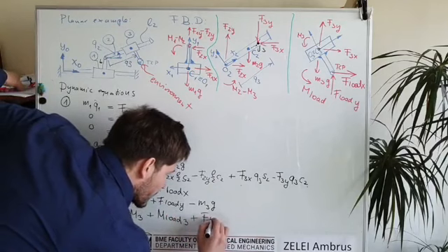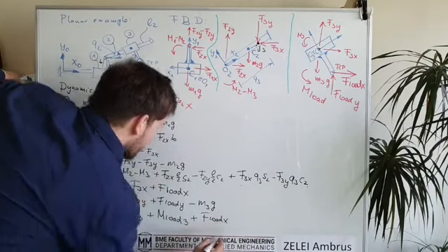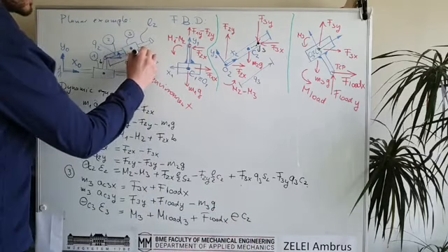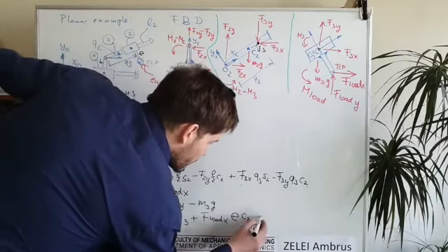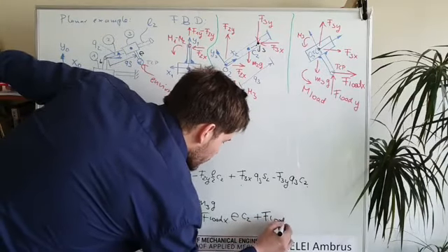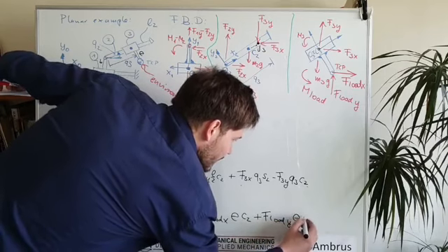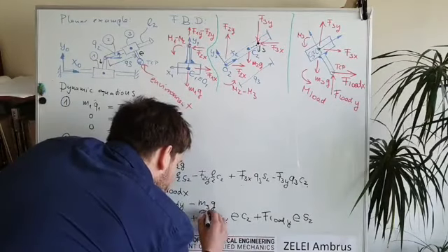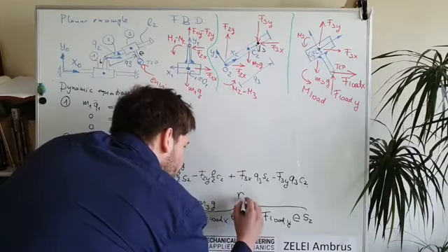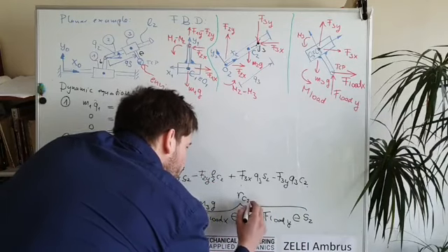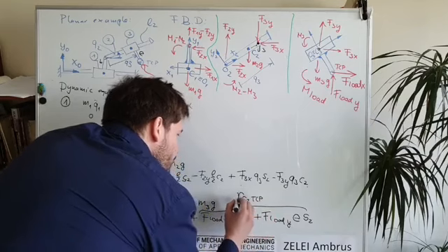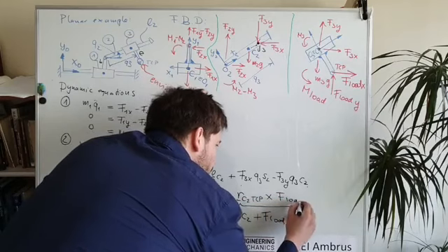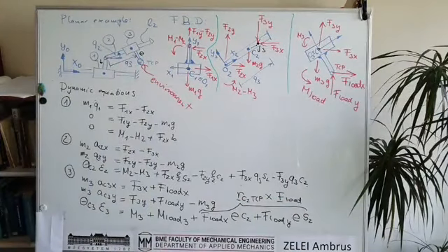So this is F load X times E times cosine q2, and E is the length of this bar here, and additionally we have F load Y times E times sine q2, and this whole term here is basically the vector going from C2 to the TCP, and cross product with the loading force. Okay, this whole term is calculated like this.